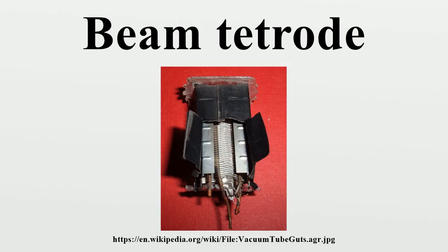The beam tetrode produces the lowest distortion of this class of tube by producing significantly less third harmonic distortion, and lower intermodulation distortion when used in ultralinear mode. Even harmonic distortion is automatically cancelled in a push-pull design. The beam tetrode can be operated as a triode, and in this mode functions more efficiently than a pentode operated in the same manner.